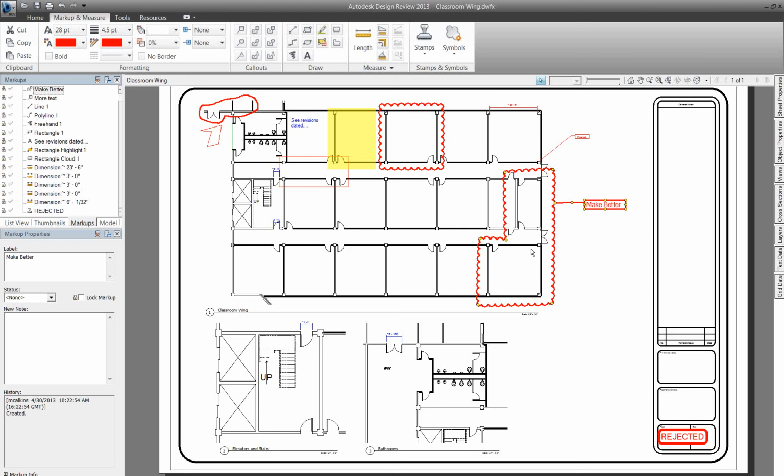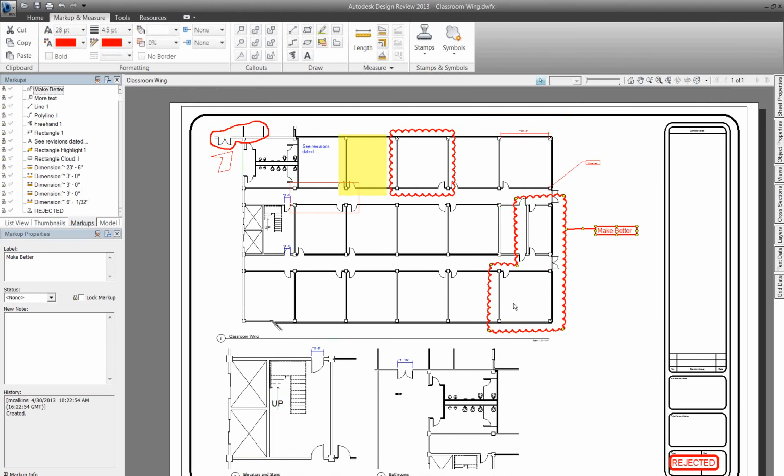Brad, yes. Your question, comment is, so we should be able to create a DWF from a DWG, then also mark it up to draw attention to certain areas for pending comment, save it, and send it out for reply and comment. Correct, that's correct. And that's why we prefer to guide people towards the DWF view or the design review rather than PDF. Not that PDF is a bad thing at all, and we know it's far more popular, but design review when you're working with Autodesk files gives you much more versatility.